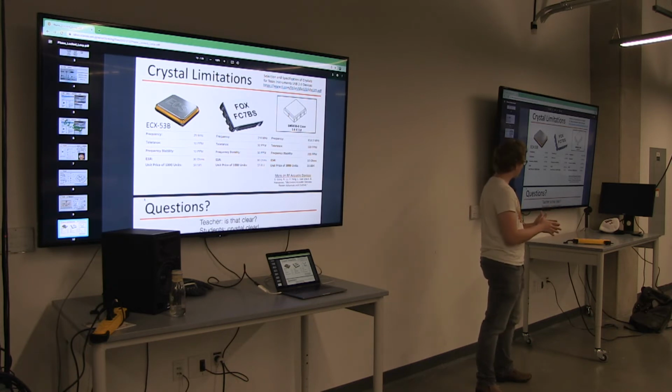What that means is that the electrical structure is actually lithography, right? It's made like a chip on top of the crystal. That means you're injecting many more errors, right? We're not very good at making geometries on chips, so you're injecting a lot more tolerance error into these geometries. So the tolerance of your frequency is higher.